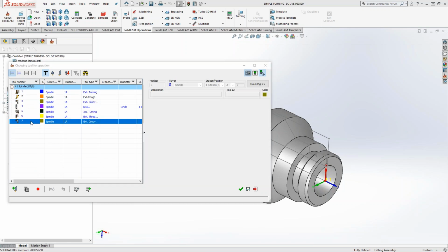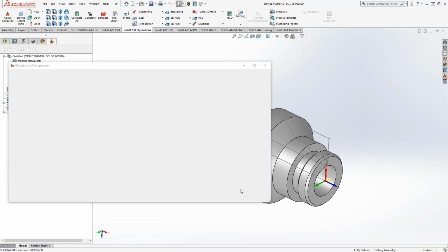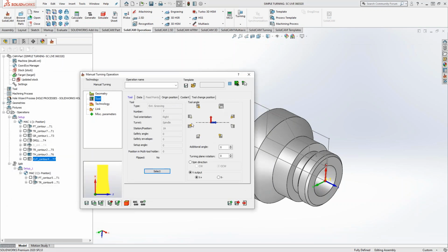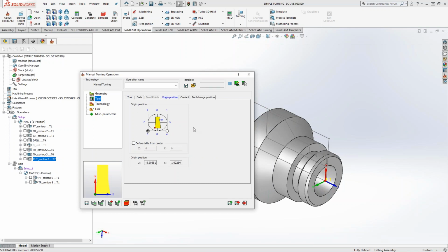And it's more to use for doing custom tools where you just need to come in there and do a double keyway or a double O-ring groove or something along those lines. It will follow whatever direction you sketch on there to a T. So maybe that first initial one you want to do a little bit of a wave, and that wave gets bigger and bigger. It's hard to explain, but you can create your own custom turning cycle based off of the sketch itself.